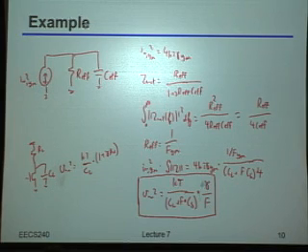But notice I have this 1 over f here, right? As a reminder, f is always less than 1, because that's just the capacitive divide ratio there, right? So in other words, what I'm actually doing is multiplying the output noise by essentially that feedback factor there. In other words, I'm increasing the output noise by 1 over that feedback factor, to be totally precise.